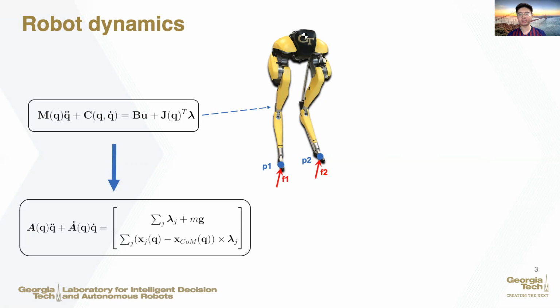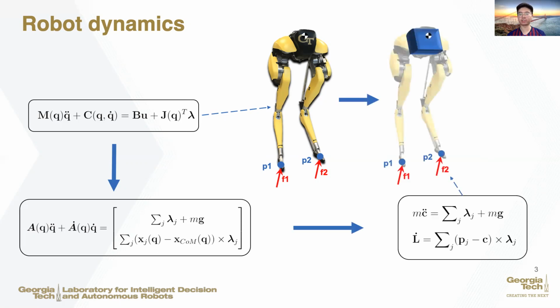However, as you can see, it depends on the full model to compute the center of mass position and contact points. To get rid of the dependency on the full model, we need to assume that the momentum produced by the joint velocities is ignored. Therefore, the complexity of optimization reduces significantly by planning on a simplified model. However, sometimes the angular momentum produced by the lower limbs matters when trying to achieve highly dynamic motions such as running. So it is also important to account for the whole body dynamics, which the simplified model cannot capture.